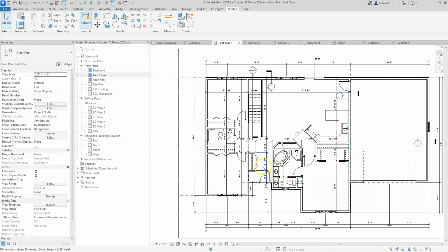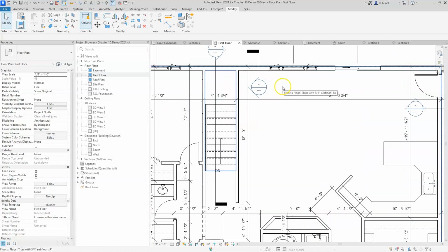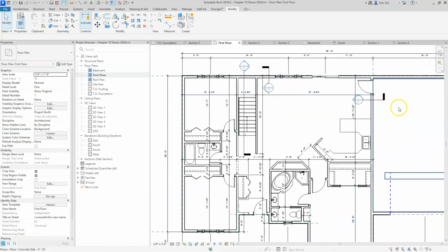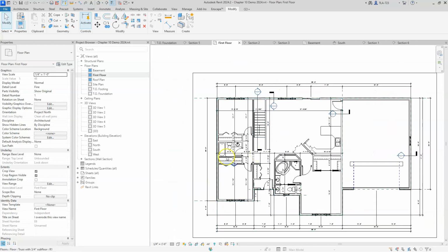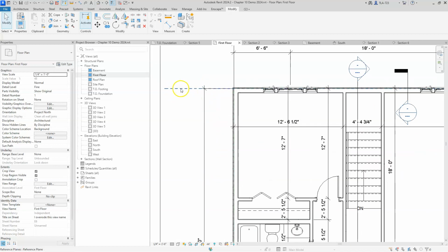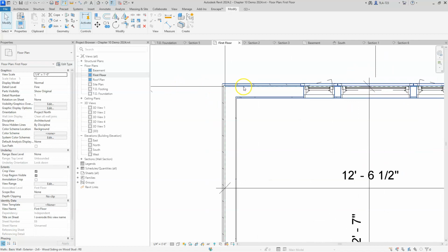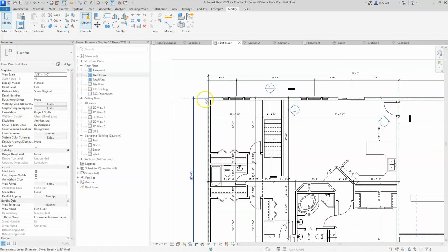I just wanted to make sure everybody understood how to edit a floor and cut a hole in it if necessary. So the biggest takeaway here that I want you to have is the boundary. The boundary of that floor needs to align with the outside face of stud, as mentioned multiple times before, but for whatever reason, that is one of the concepts that folks just typically have the hardest time conforming to or getting.